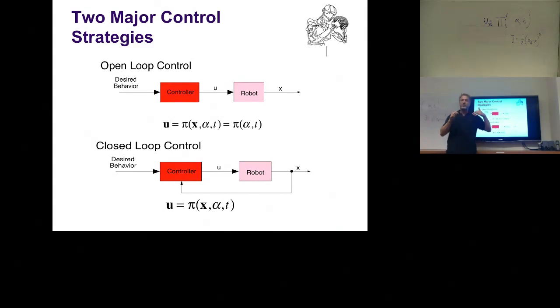Now, where is this useful? We talked about this for a moment, but we just repeat. Most of the time, you always want to get state feedback. You don't want to run around blindly and hope you get somewhere. But if in your feedback loop, like shown here, there's a strong delay, like for instance, in our human nervous system, the delays are quickly 30, 40, 50 milliseconds, or even 200, 300 milliseconds. It sounds very little, but for control systems, it's terrible. And if you have delays, for instance, using a feed-forward command in order to do a fast movement and only turn on feedback control when you are close and slower moving is often the right thing to do. So that's what we often do.